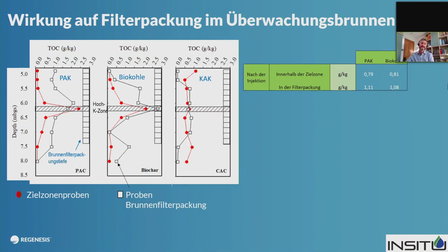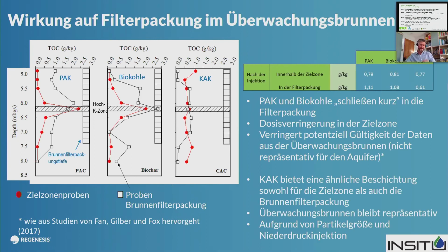data. You can see with the colloidal activated carbon over the treatment zone that there's a good correlation between the amount of colloidal activated carbon that went into the formation and that's in the well, and so the well has been treated the same as the subsurface as well, so it can be said to be representative. And hopefully what I've just said there is being said in German.